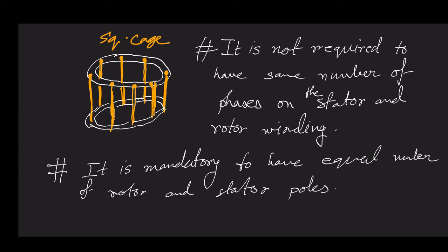One is magnetic field lines are like stretched elastic rubber bands. They always try to restore the minimum energy path. And that minimum energy path, if you recall your last semester class, all the energy storage takes place across the air gap. So in other words, if we reduce the amount of air gap, we are able to reduce the amount of energy in that circuit.